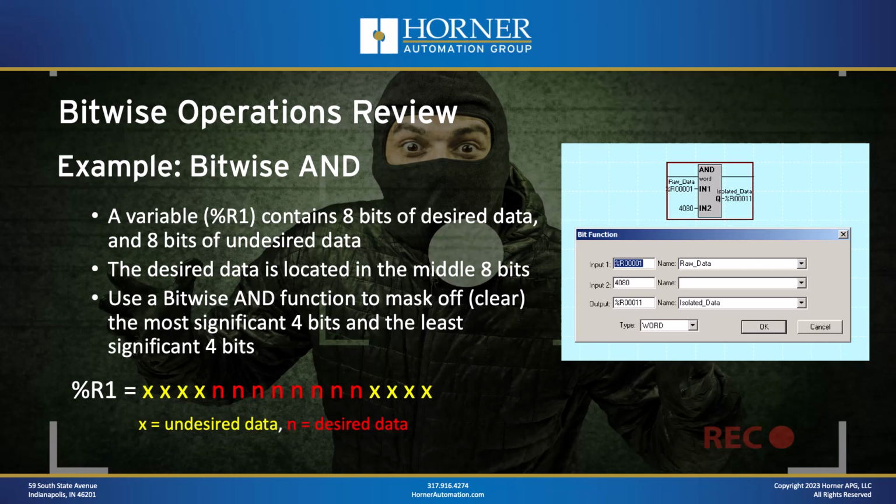So the way an AND function works is you take a variable, you AND it with a value, let's say a Boolean value, which is converted to decimal when it's input into Cscape, and that value represents a bit pattern. So with the AND function, when you're creating a mask, everywhere in your mask value where there's a 1, that bit will come through.